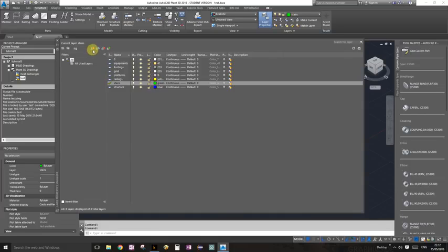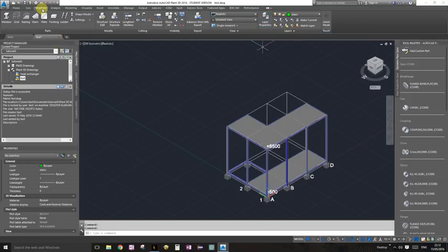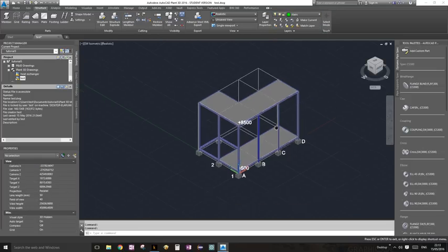So you guys already know, just click on this button here and type in your name, choose your color, and then get out of this layer properties window. Again, layer properties can be accessed from the ribbon structure under the palette layer drop down box, and the layer properties button there. We're going to make sure that stairs is the most current layer that we have chosen.